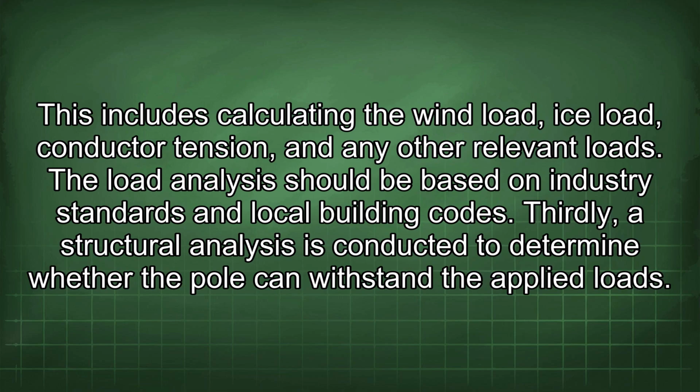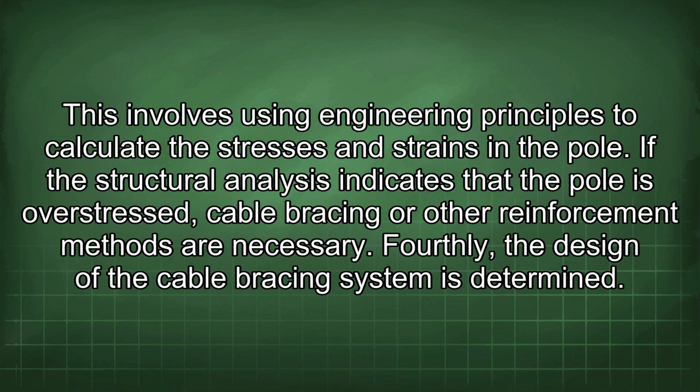This includes calculating the wind load, ice load, conductor tension, and any other relevant loads. The load analysis should be based on industry standards and local building codes. Thirdly, a structural analysis is conducted to determine whether the pole can withstand the applied loads. This involves using engineering principles to calculate the stresses and strains in the pole. If the structural analysis indicates that the pole is overstressed, cable bracing or other reinforcement methods are necessary.